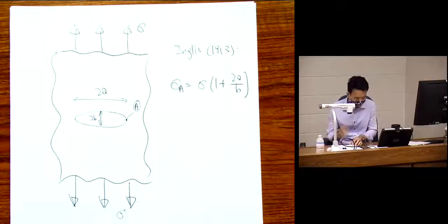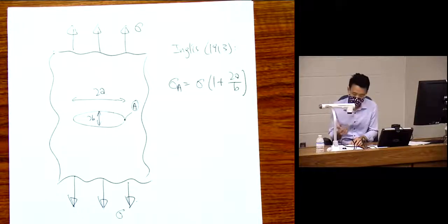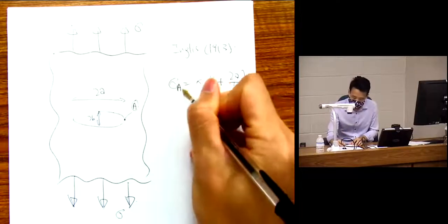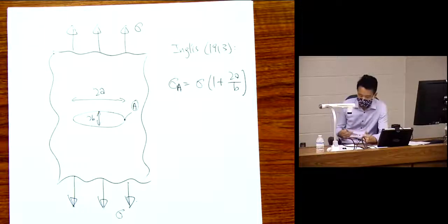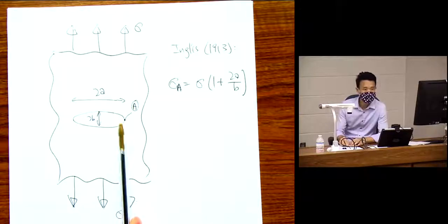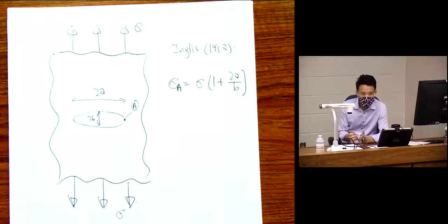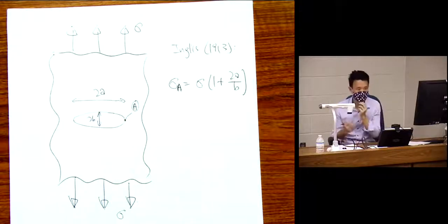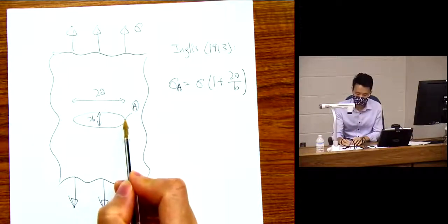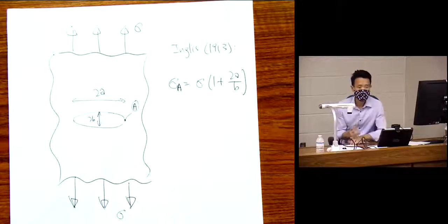Now, but what we can get is to extract more insight from this, right? This is a solution that we get. So Inglis went into a bit more detail, right? But what we really want to understand is to make this crack extremely sharp, right? Because the flaw is going to be small compared to the body, typically. Why don't we find the stress at the crack tip as we push this crack to be extremely sharp, right? But how do we do that analytically?